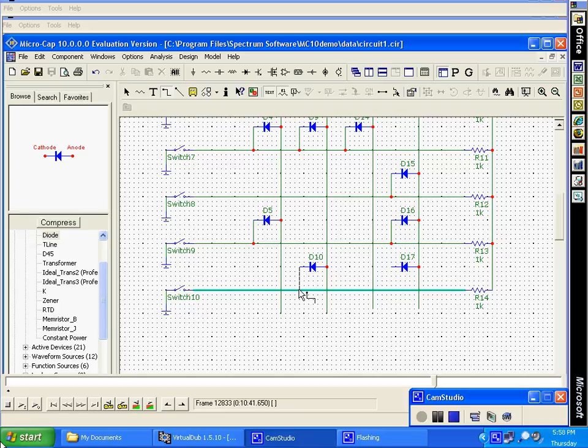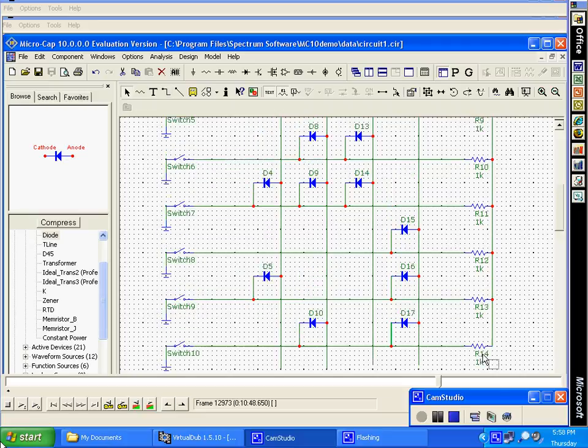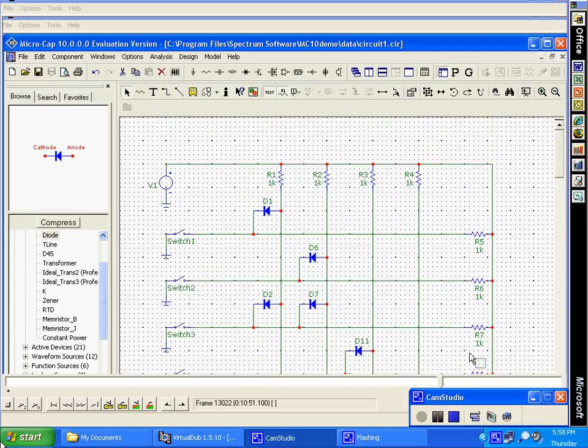What we need to do is add node numbers to this so we can set up our testing. So when I click on that icon, notice all the node numbers appear. So we now have ways that we can identify nodes for the transient analysis. So we go up here and hit analysis, and we pick transient. Now we have some numbers here. This is implying that we need 4 different graphs, and these are the nodes.